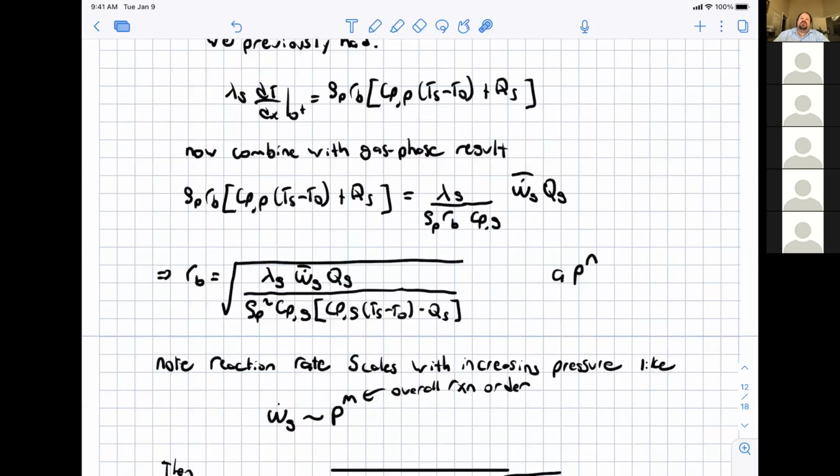Just because there isn't enough known about the parameters of the propellant species to even do a formal supercritical combustion model for them in the first place. But anyways, this here is constant. So basically everything here, except for maybe the surface temperature, and the average reaction rate is basically constant. But again, we will assume that the surface temperature is a constant. That is actually absolutely not true, but we will assume it's constant anyways.